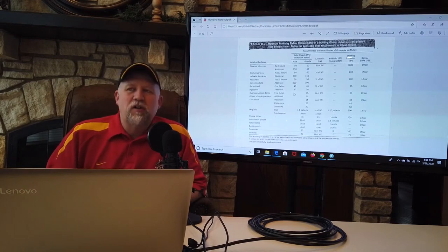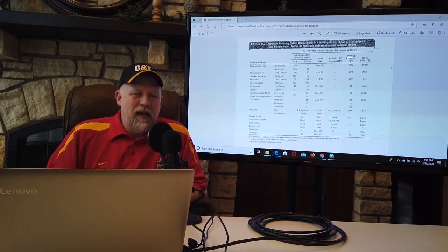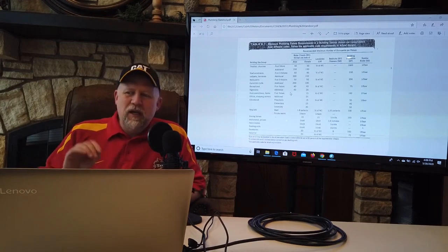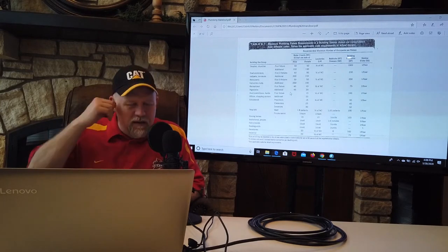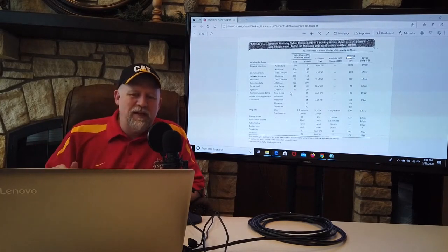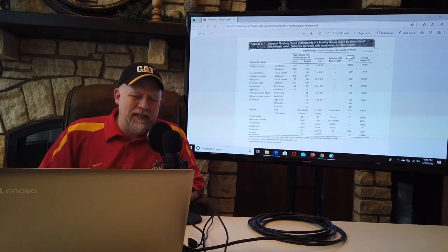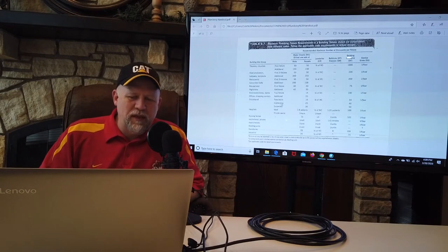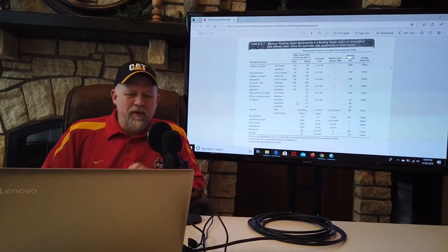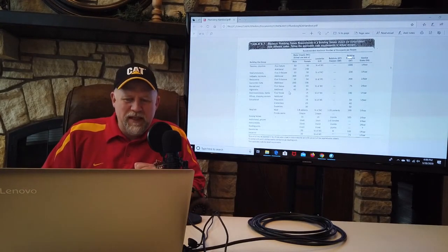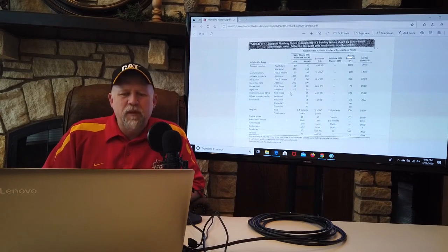All right. Why is it different based on occupancy? Think of a theater or a church. Most of the time, events in a theater or in a church are limited to an hour, maybe 2 hours. In other words, I go to the assembly area for an event. When the event is over, everybody leaves. They are not in there all day like a business is, or a school like an elementary school where people are there all day. All right. So the ratio of water closets per person is different based on what the people are doing.